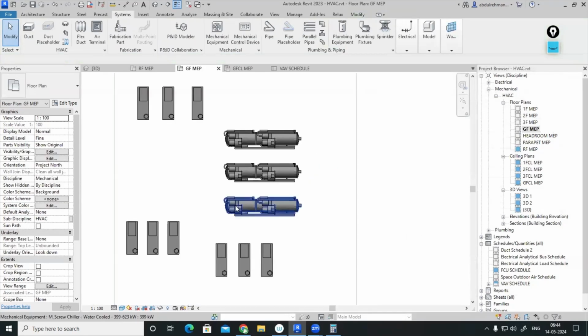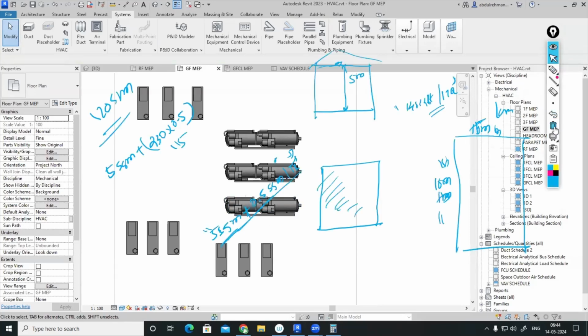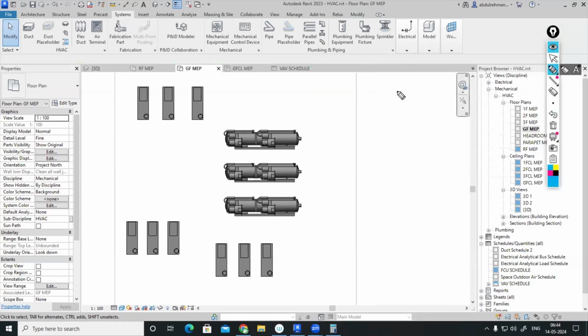And in the chilled water circuit classes, we have studied when we are using the pump for the chiller, manifold arrangement we can use, manifold pumps we can use. For example, when you are providing the chilled water primary loop, we are having a single pump option. If this is the inlet to the chiller, here we can use a single chiller, single pump. Single pump connection will be there, but the disadvantage is even if 1 or 2 chillers are not working, then the pump, adjusting the RPM will be difficult even if there is VFD. So that is not economical.